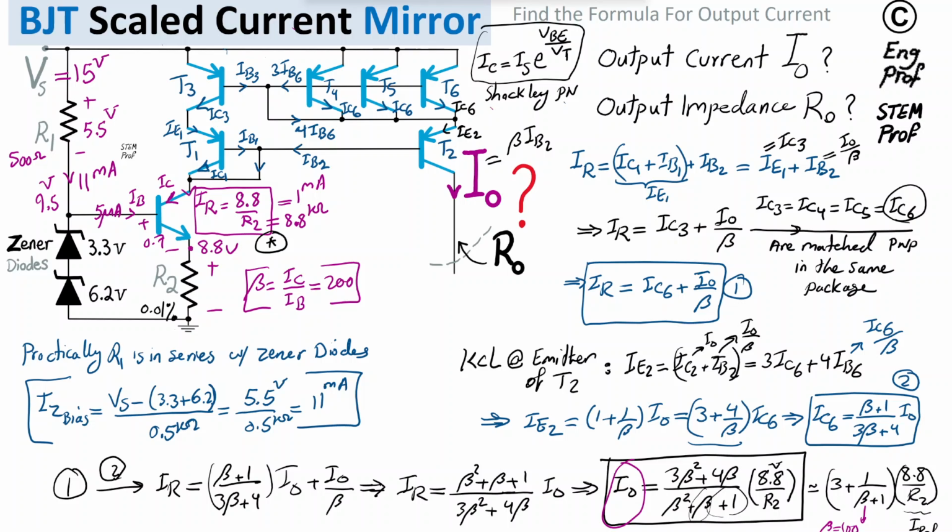When we have this sort of connection, at the emitter of this transistor we are seeing the bunch of collectors wired to the base. What happens is that a resistance proportional to the base resistor, or the equivalent resistor of these transistors, will show up at the collector of them and at the emitter of this transistor.